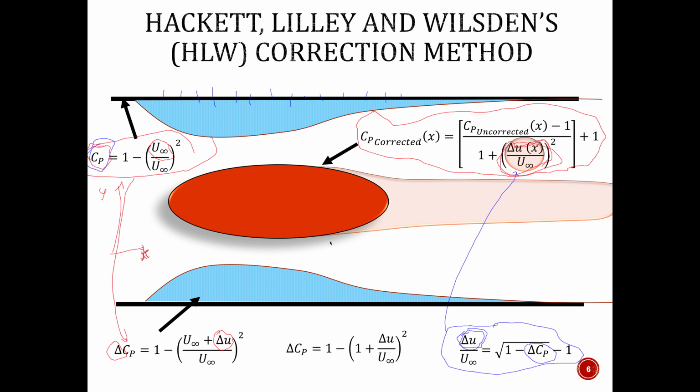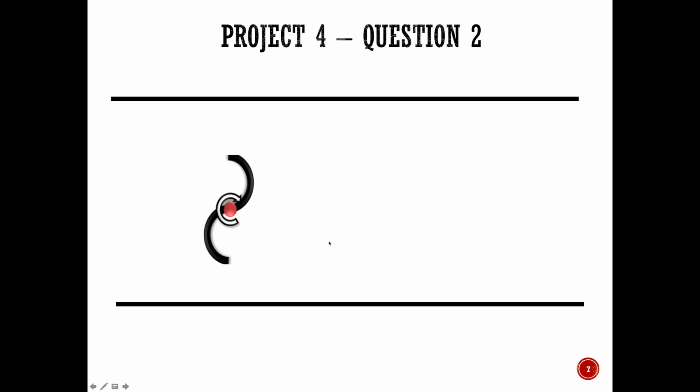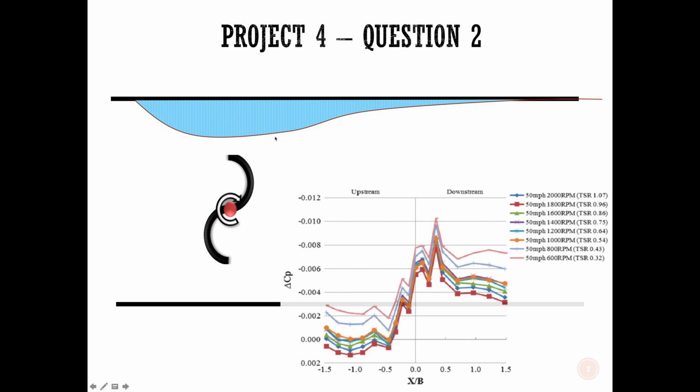So in the homework, what you can do is, I kind of put a model in here. In Alpin's and Ian's papers, they put the vertical axis turbine in the tunnel, and they actually took tunnel wall measurements based on the scale of the rotor. You can see that in figure 14 in their paper.